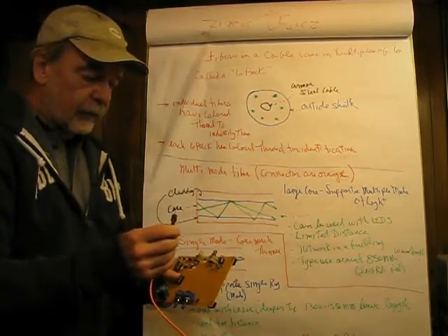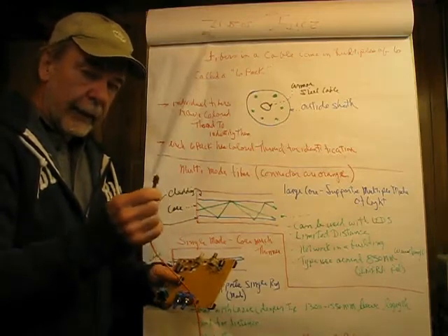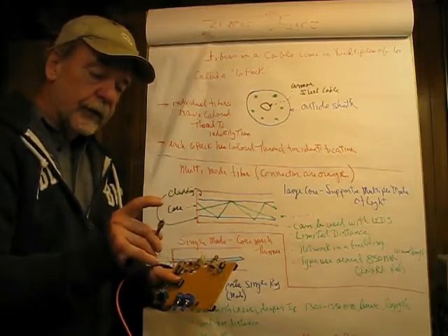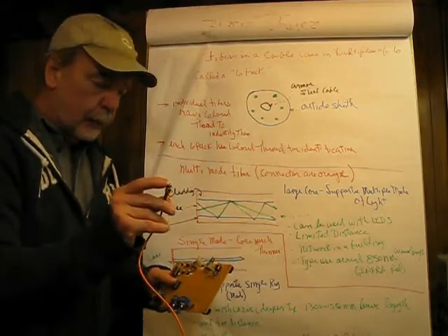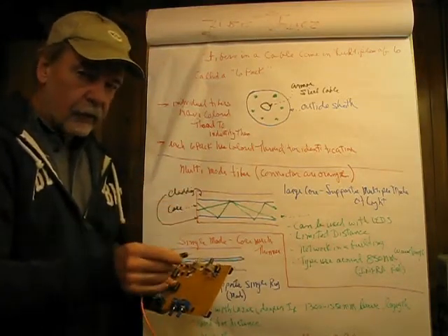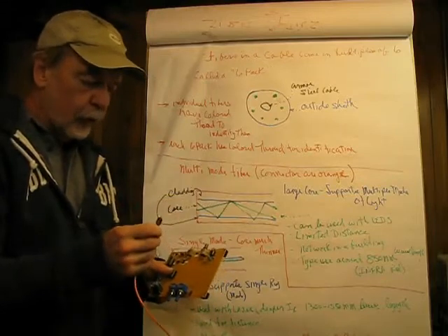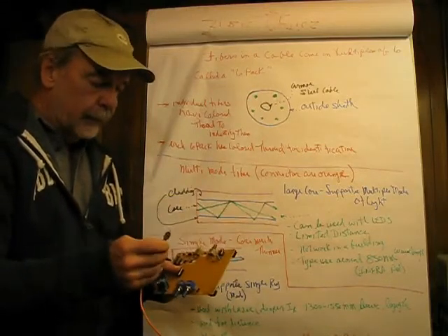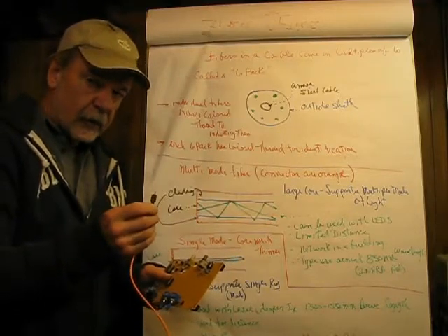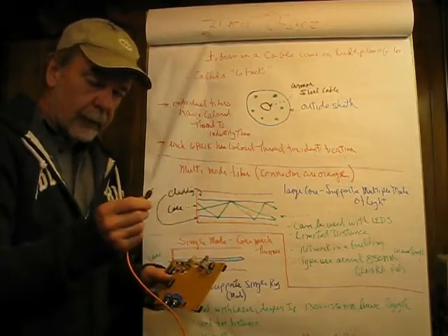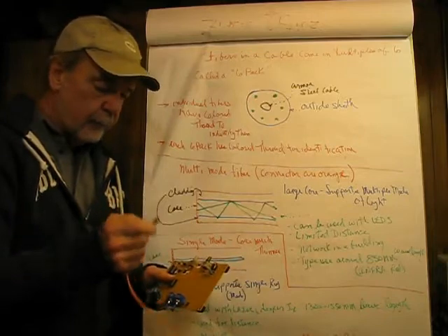The one thing you have to be very, very careful about when handling one of these is you don't get your fingerprints on the end of that. Because a fingerprint at these wavelengths is a mountain. It causes all kinds of issues. Namely, it reduces the received power level. There are kits available to clean these, and you have to be very careful with them.